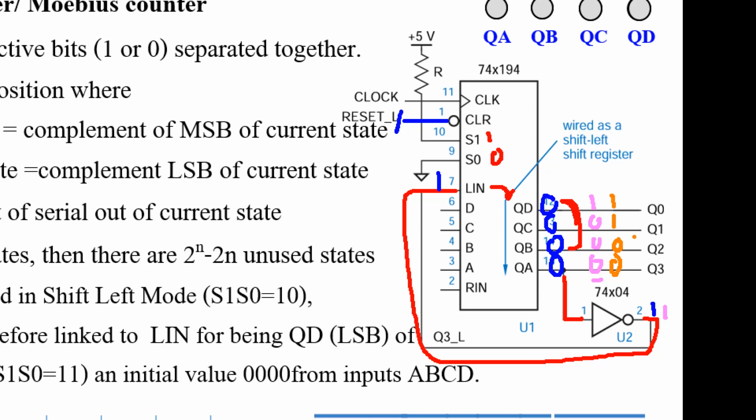Okay? And this bit is 0, right? So when inverted, it is still 1. Okay? This bit is still 1. When the clock ticks, copy these 3 bits, 110. Okay, shift down and read data from in, which is 1.